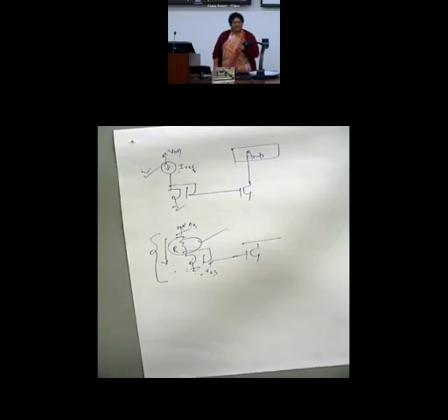So if my bias current is changing, my small signal parameters are changing, and my gain will change. That means I cannot guarantee to my customer a gain of 10. I will say you will get a gain between 9 and 11. So there is a range, which means reliability is not 100%. You cannot say with guarantee.